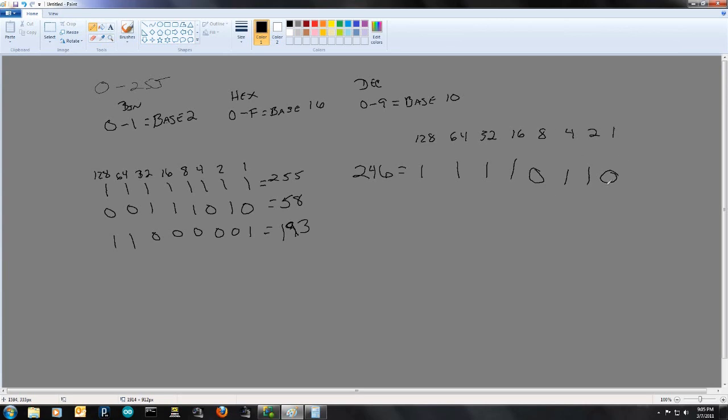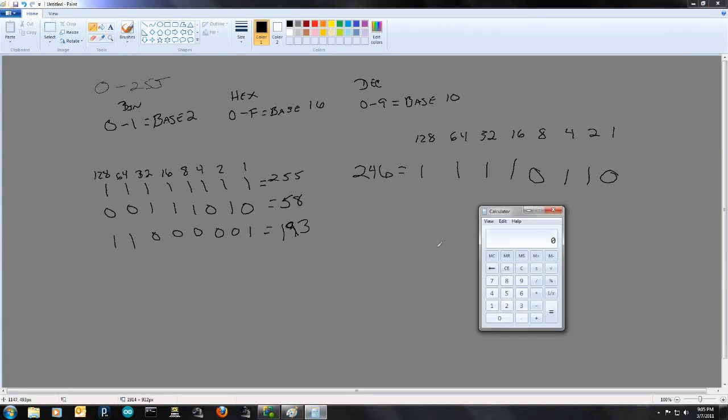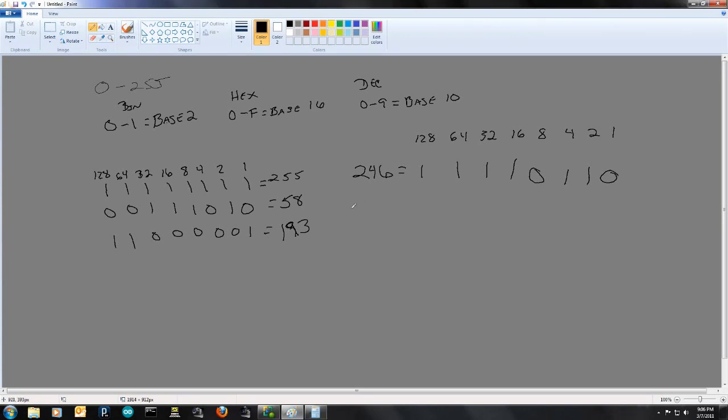1, 2, 4, and 8. And of course, if you add up all these numbers together, 8 plus 4 plus 2 plus 1 equals 15. So if you're only using 4 bits, you have 0 to 15. But right now we're using 8. Most common, especially in communications, when we start developing our own serial communications protocols, we're going to want to use 8 bits, with the standard N81. And we already had a little bit of serial communications when we chose 9600 as our speed. But anyways, let's not get off track here.